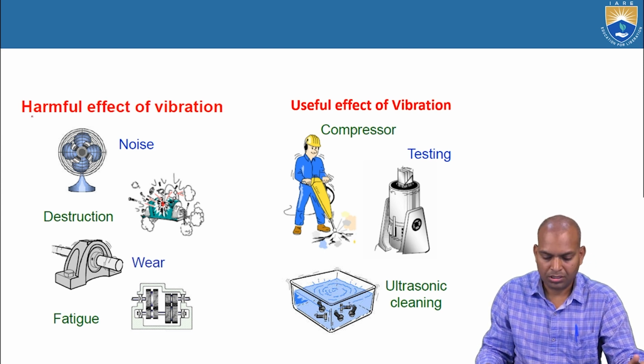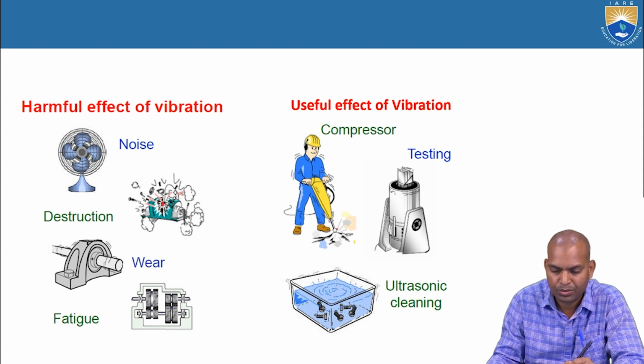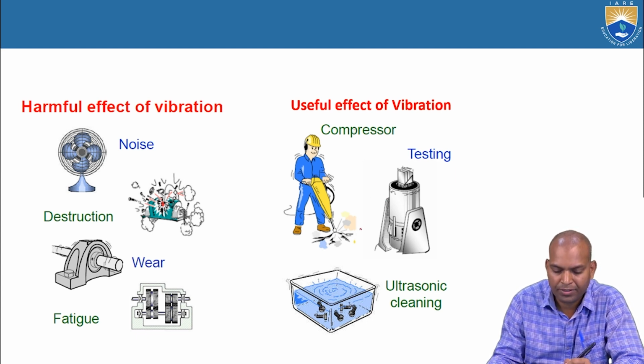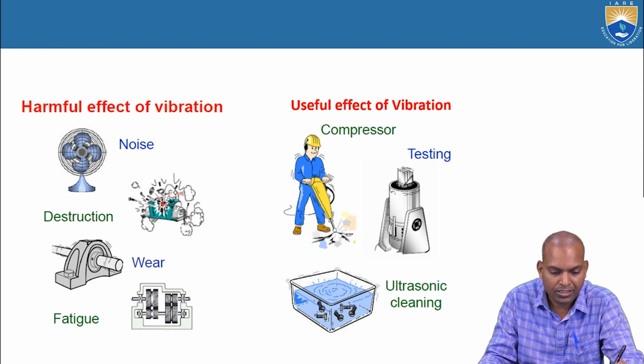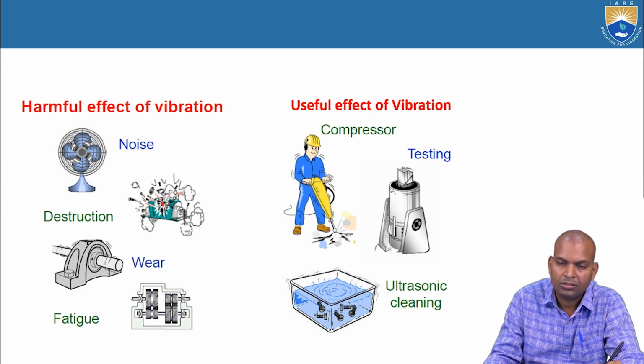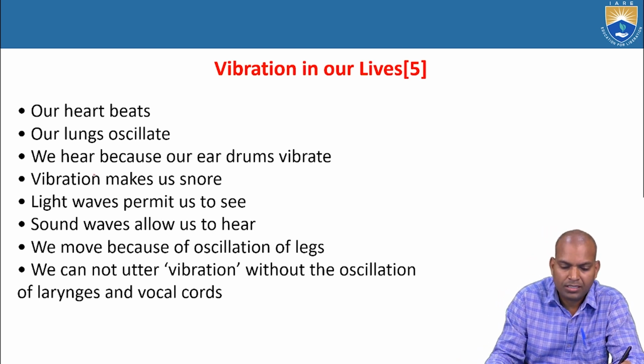And what is the useful effect of vibration? Useful effects of vibrations are such as in the hand drill or compressor, which use vibrations effectively. And for testing, vibration shakers are useful for testing purposes. Those are also useful effects of vibrations. One more, ultrasonic cleaning is also a useful effect of vibrations. Here, this noise takes place because of the wearing of the bearing inside the table fan or ceiling fan, causing tremendous noise. That is harmful for the human body. And also some destruction purposes are useful. If we give the vibration at the basic foundation, the whole structure will be demolished.